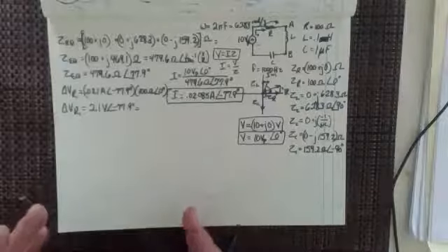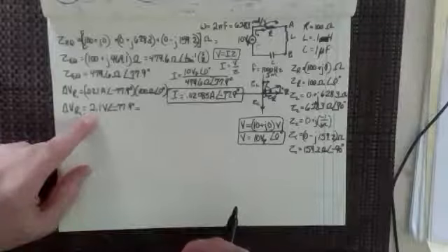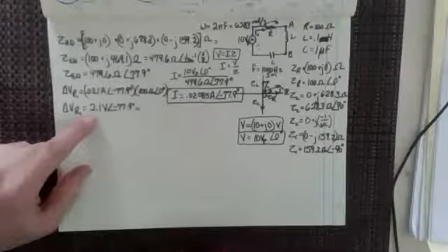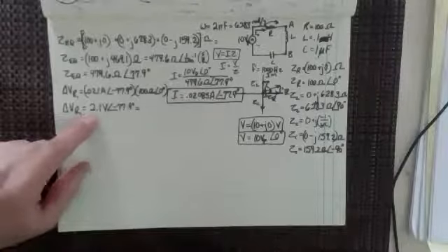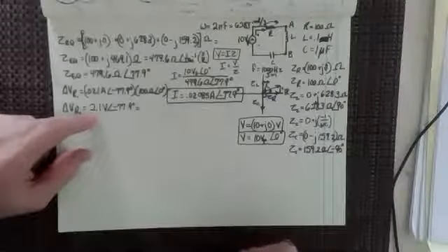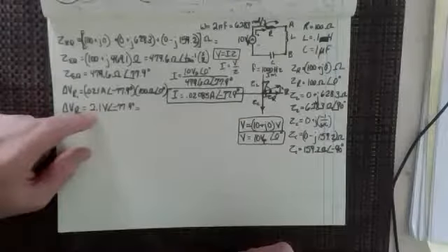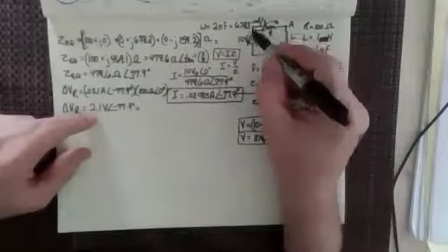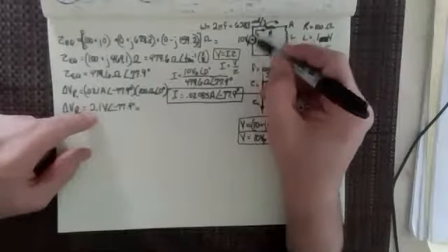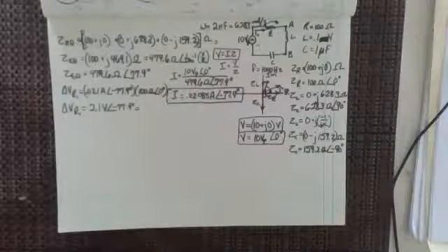And now what we have to do is turn this phasor form of the voltage drop back into its complex number notation form, the A plus JB form, so that we can subtract it from the 10 volts that we started off with, right? Everyone realizes that it's 10 plus J0 volts. So let's find out what the voltage drop is. And how do we do that?